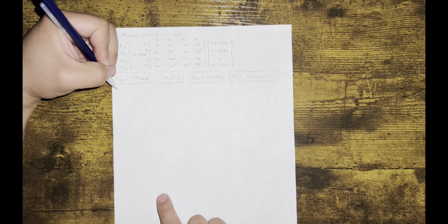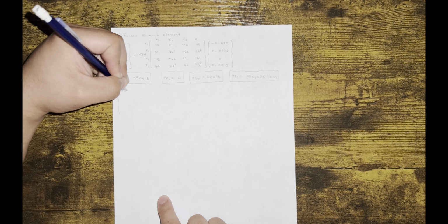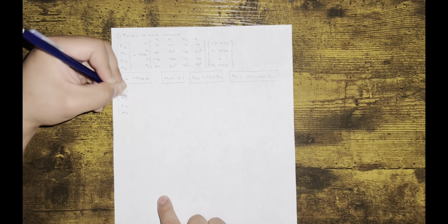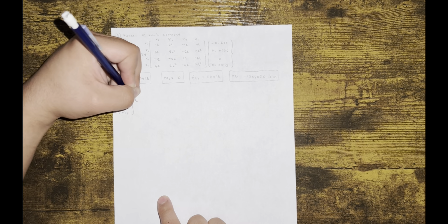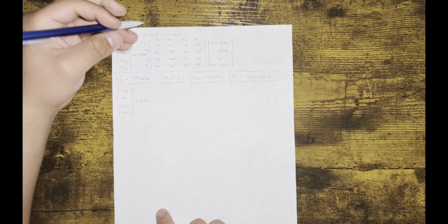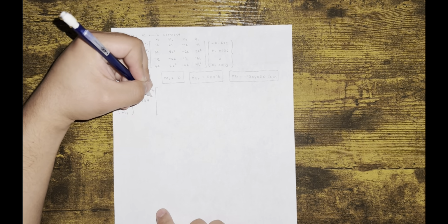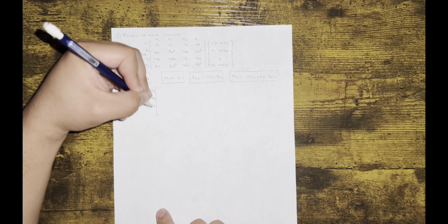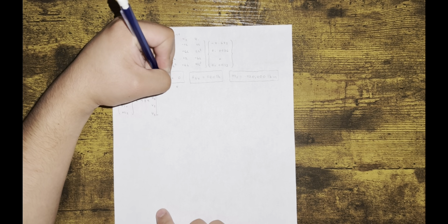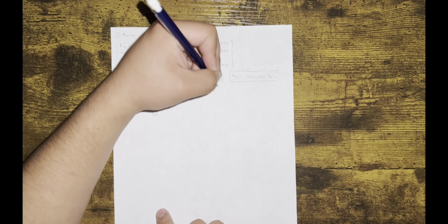So I'm gonna go ahead and do the same step, but now for element number 2. F2y, M2, F3y, M3. Okay. And again, the flexural rigidity is the same. Let's go ahead and do V2, Phi2, right? This one's between nodes 2 and 3. So that changes. V2, Phi2, V3, Phi3.